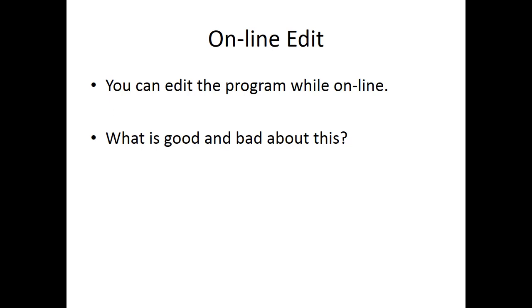Because what's good or bad about this? Well, if you go online and you make a bunch of edits, then you have to upload that program back to your computer. Otherwise, those changes are only on the PLC. They're not on the offline program. So you get in trouble when the offline program, which a lot of times is the master program that somebody is counting on to be able to download at any time if the RAM is lost, no longer matches the one that's in the processor. Then it's going to erase it, and so any changes will be dismissed.